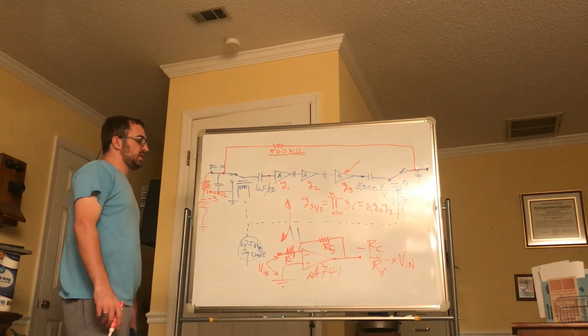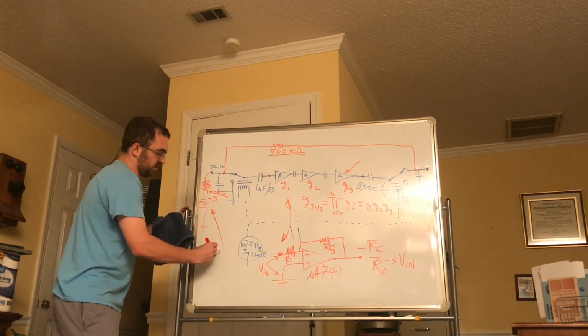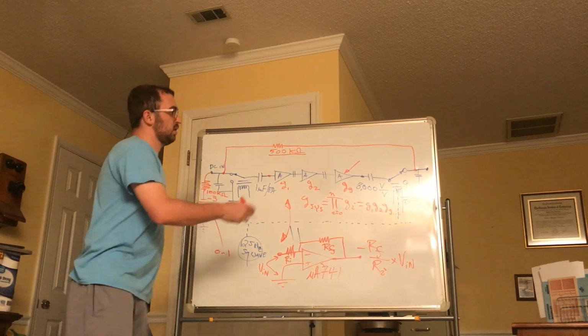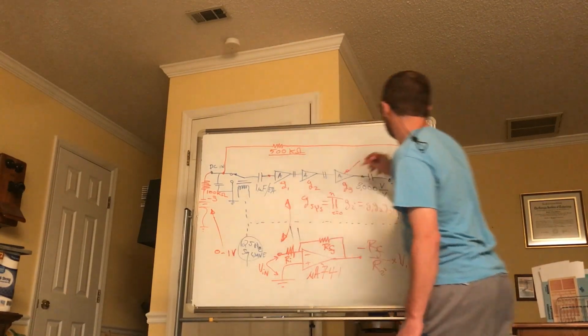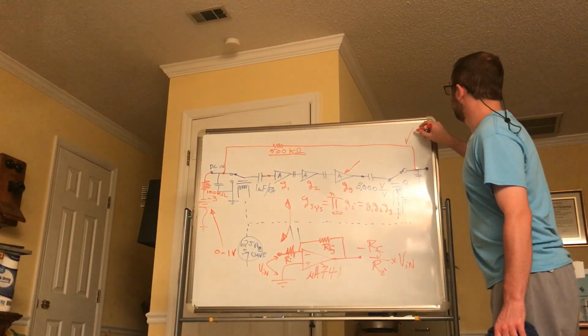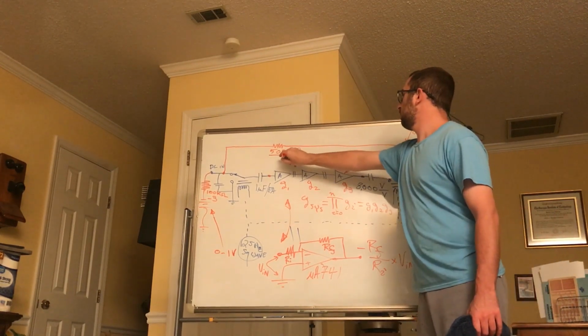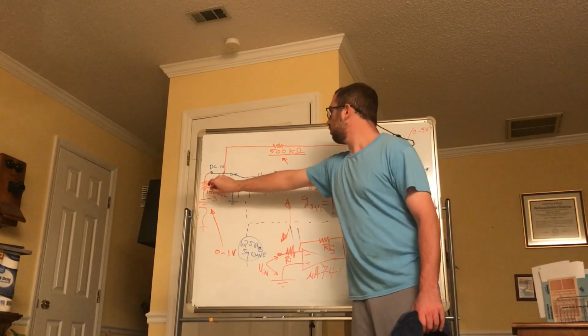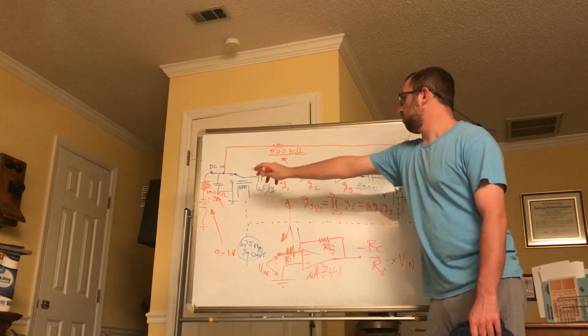All right, so this is our DC amplifier. So this could be a thermometer, which would have a range of 0 to 1 volt, and then out here you get very reliably 0 to 5, or so on. And you can fiddle with these values to get exact gain. And of course, you flip it around because it negates it.